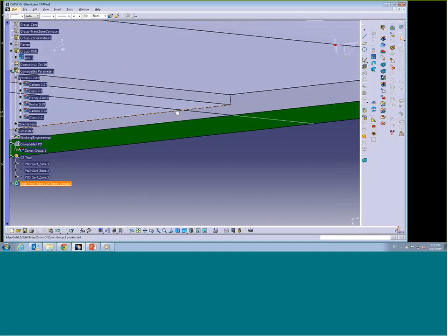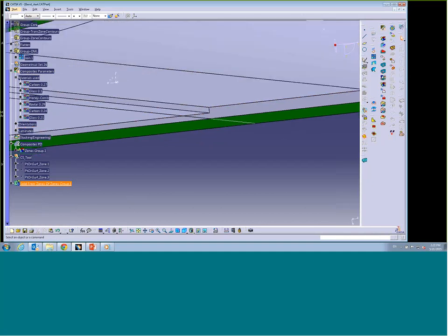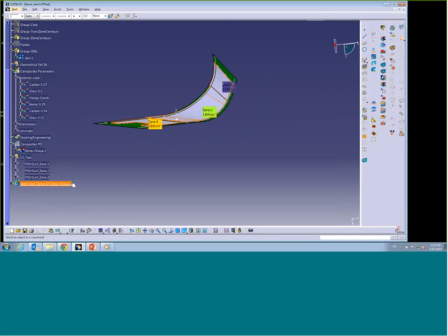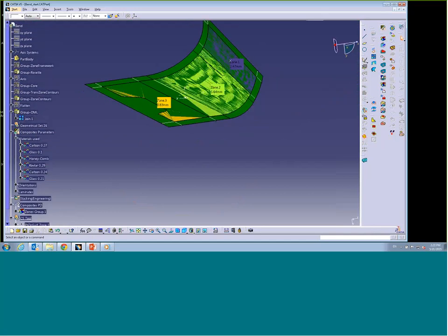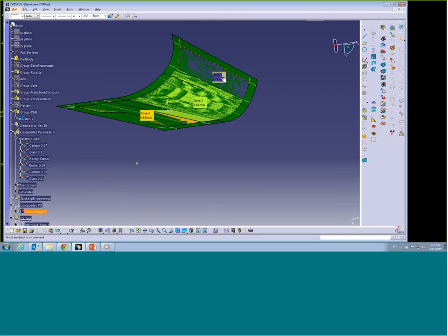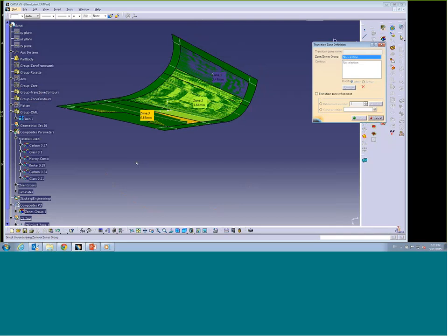To create ramps, I'm going to use now what is called transition zones. All right, so I'm going to get rid of that fella. And I want to create transitions. So again, I have some geometry pre-created for transitions. So that was transition zone contours. And let's say I want to transition from the thickest zone to the next one up to here. So I'm going to create transition zone. The underlined zone is this fella. And just select create a contour. Same as before. I'm just going around the zone.